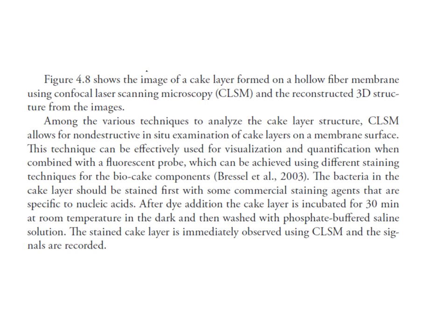To use the equation in the previous slide, you have to know the information on particle size and porosity. Particle size can be measured using laser scattering techniques. However, the porosity of the cake cannot be directly measured using conventional techniques. Fortunately, recently, people have invented the technique called confocal laser scanning microscopy.